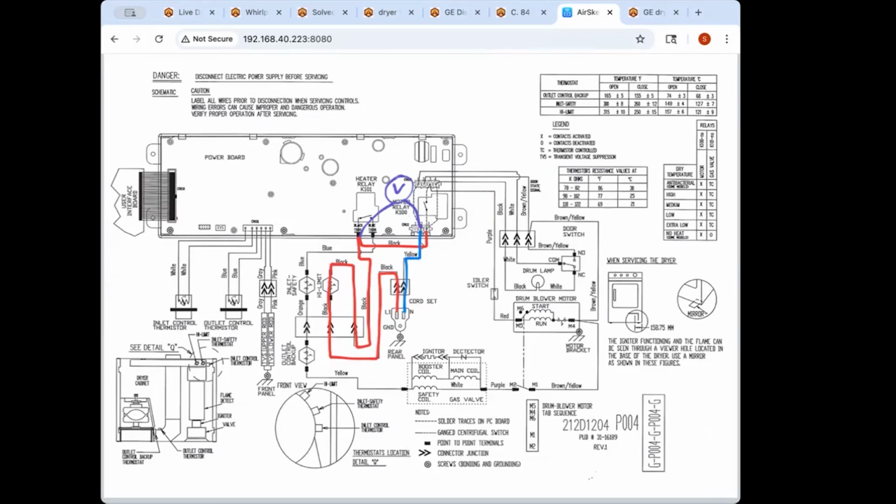Yeah, and that's what I would say to that. Even if they are a little on the expensive side, they shouldn't be. These are little cheapo parts, but even if they are gouging you for them, you're giving the customer a better, much more reliable repair if you change all of them. Because if you just change the high limit and leave the others, you're leaving yourself open for a callback. After you check your airflow.